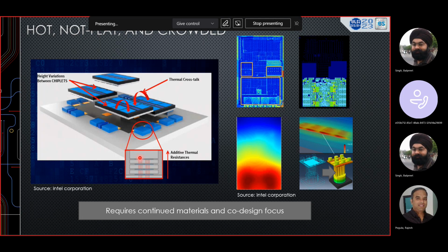But having said that, all these chiplets are within the package, right? And they are one on top of each other, maybe differently stacked and so on. Maybe the thermal hotspot is within that region itself, right? And it may not be able to spread out to the package itself. So those are some of the scenarios we need to think through as part of the thermal design, right? Does it answer your question?